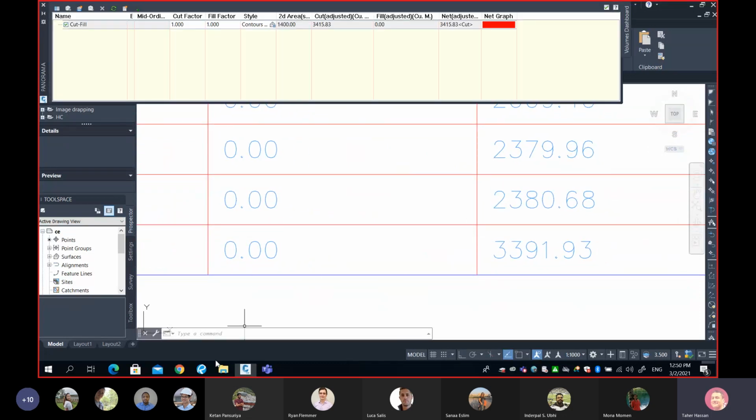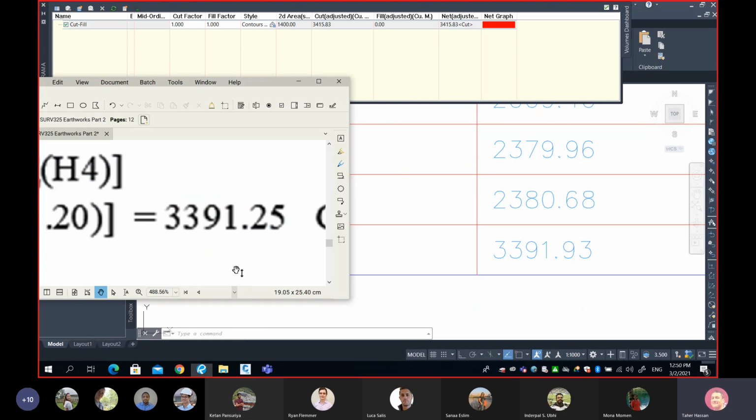So I'm going to open again the 3 numbers side by side. Do you see what's happening right now? Did you see what happened right now after I added those two magic sections? It's closer. It's very close, which means you can see the methods, all of them, they are accurate, all of them, they are correct. However, it was my fault as a user to simply not add enough sections for the software to estimate.